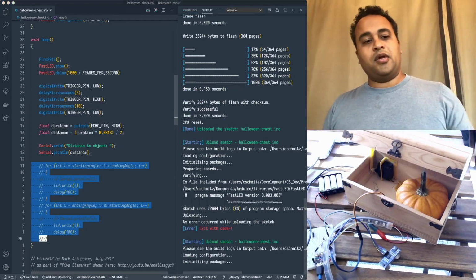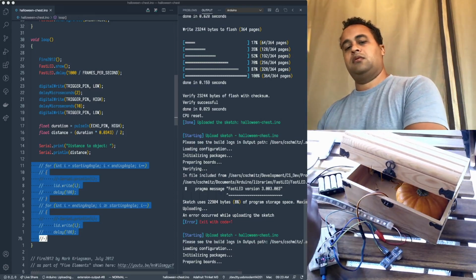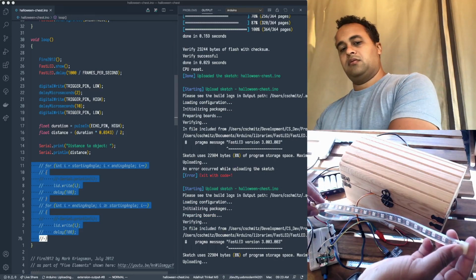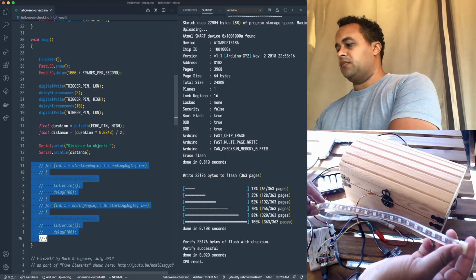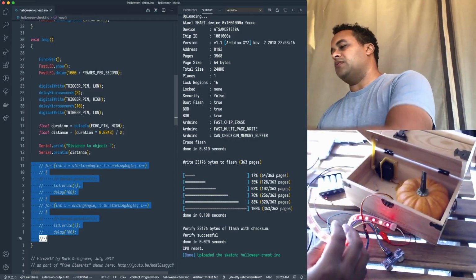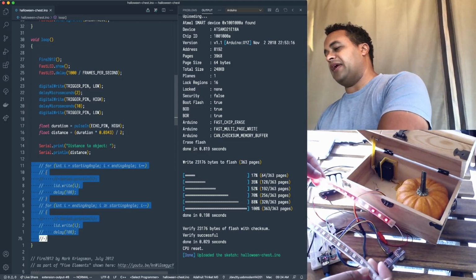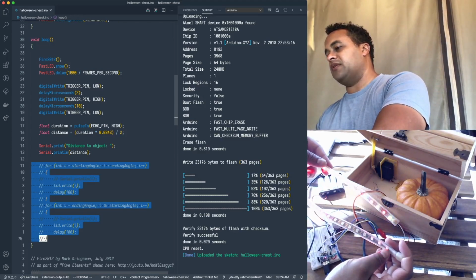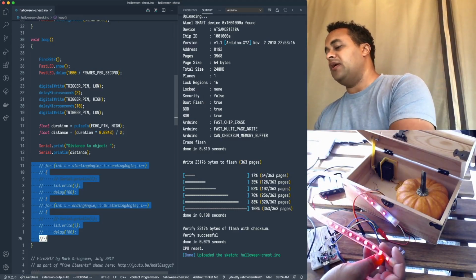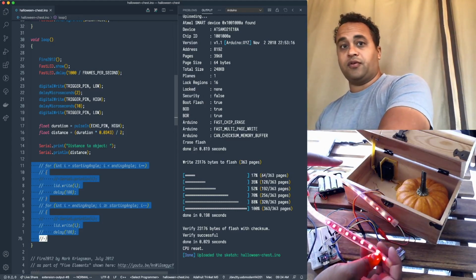So now, if we comment out the servo loop and we upload it, once the new code is up, there we go. We'll see that the light pattern moves considerably faster. This is roughly the animation speed that we should have been expecting for it. But it can't move at this speed, because the light pattern is moving in frames conceptually, and we can't advance the frames at this speed if we're also waiting for the servos to open and close.